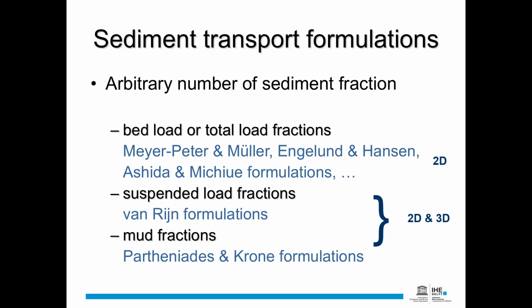And if there is quite a bit of mud involved in this model, in our case, then maybe we need to also use the Partheniades and Krone formulation for that. So all these are possible to use in Delft3D. And an arbitrary number of sediment fractions, practically up to 99 different sediment fractions and sediment types, are possible to be used in Delft3D as well.